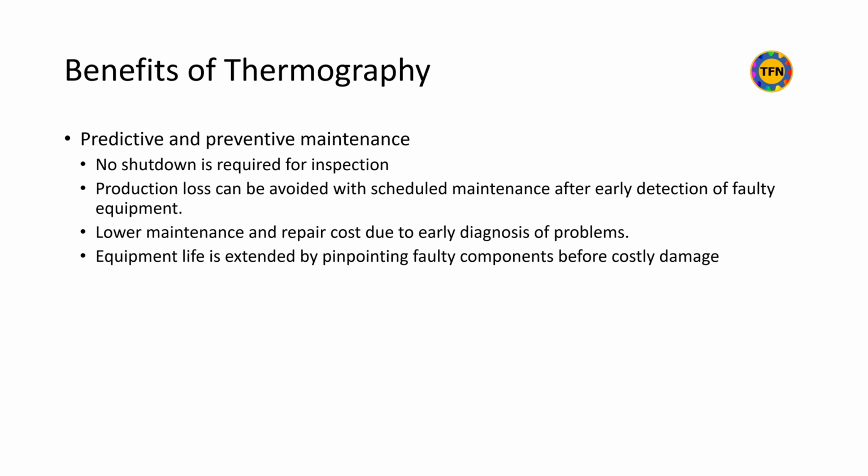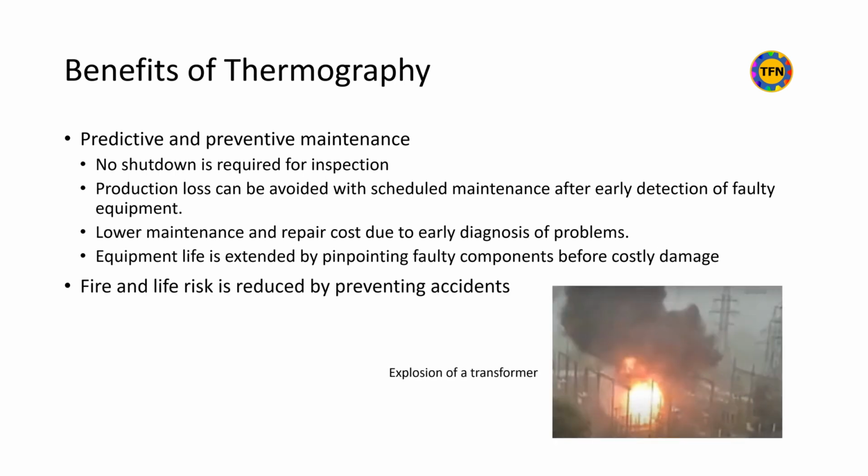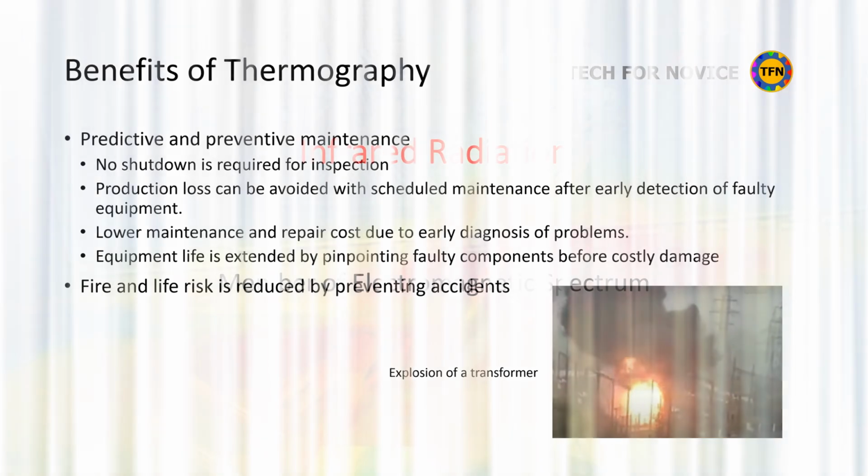Benefits come from the advantages. Thermography is a predictive and preventive maintenance tool. No financial loss with frequent inspection of plants, as no shutdown is required. Frequent inspections lead to early detection of faulty equipment, allowing scheduled maintenance instead of emergency shutdown due to severe damage.